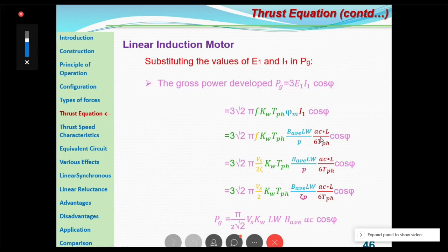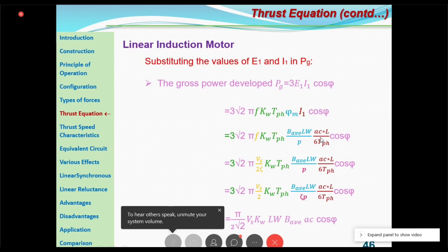Next, we are moving on to the equivalent circuit of the induction motor. As you know, in an induction motor you have a stator. The stator has a stator resistance and leakage reactance, and you have an exciting circuit R0 and X0, that is the no load exciting circuit. And here the secondary will have a resistance and leakage reactance, and the induced EMF will be sE2.